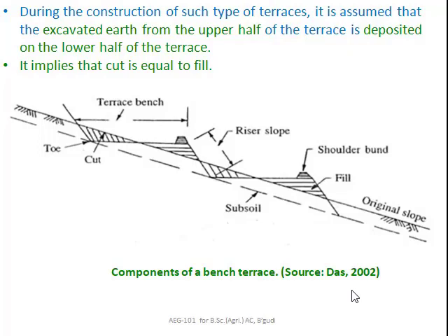It has some limitations. What are those limitations? Initially, it disturbs the soil. It reduces the productivity for the first 2 or 3 years. It requires intensive labor and investment for construction and maintenance. It needs skill for proper construction. This type of terrace field with the interval slope consumes much land.